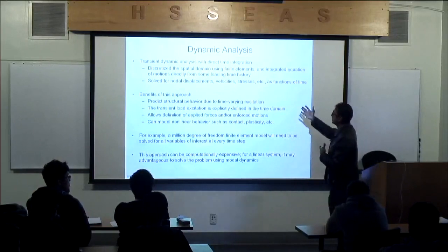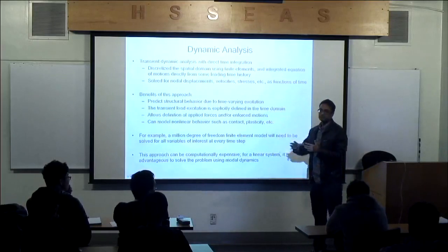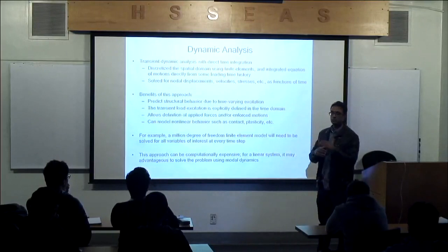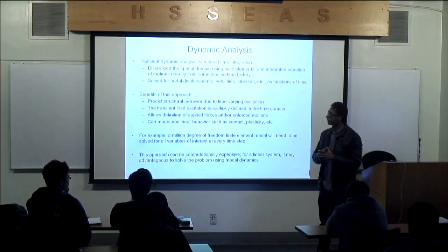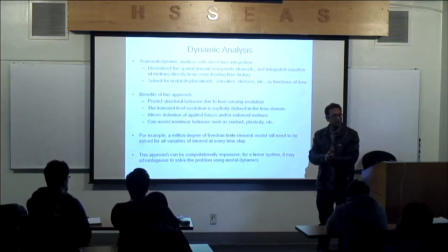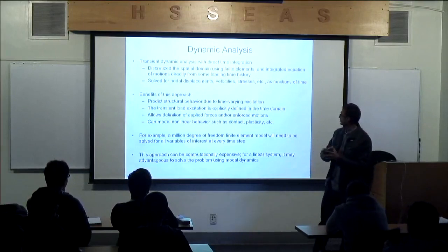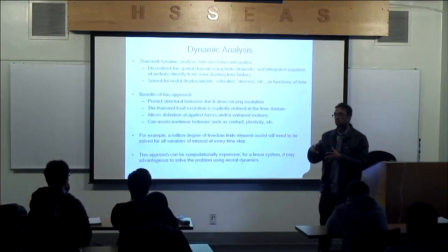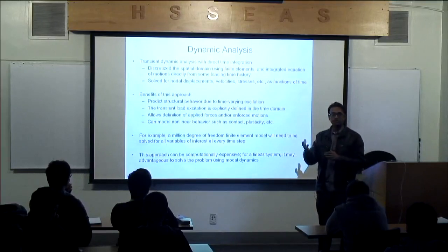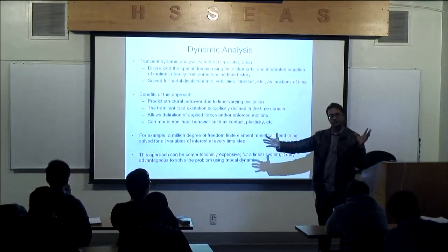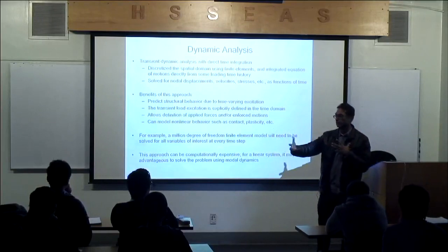So what are the benefits of this approach? The benefit is that you can predict the structural behavior due to a time varying excitation. The way we did it, you can predict that behavior very well. It works for nonlinear problems, contact problems, plasticity, and so forth. It allows applying forces and enforcing motions. You can also explicitly define the transient load as an explicit function of time. So I can say, hey, this forcing function, excitation, behaves this way as a function of time. I can explicitly put that formula in.